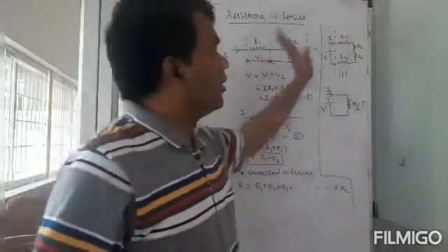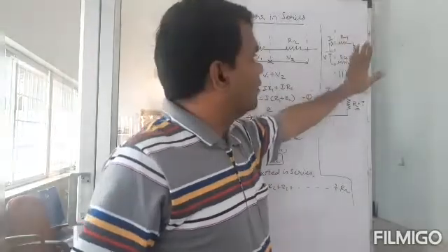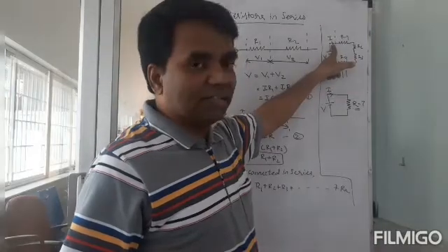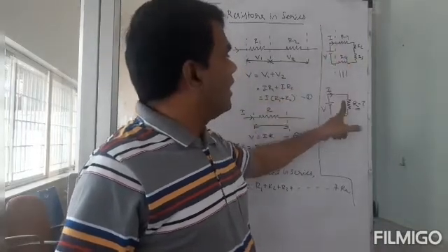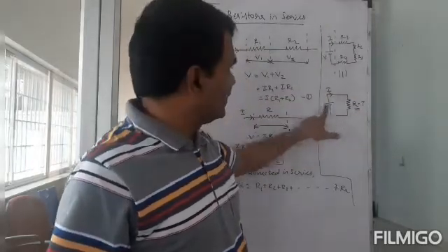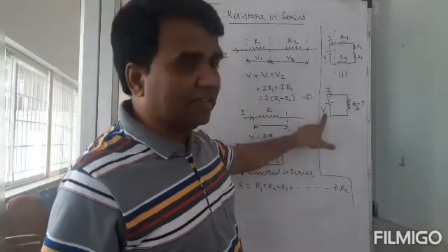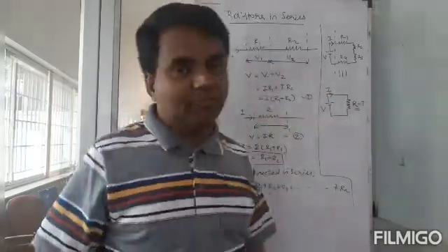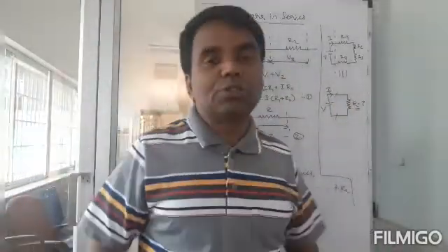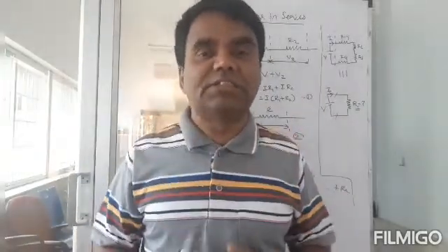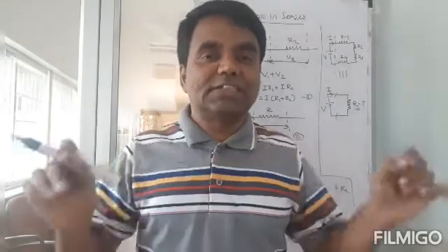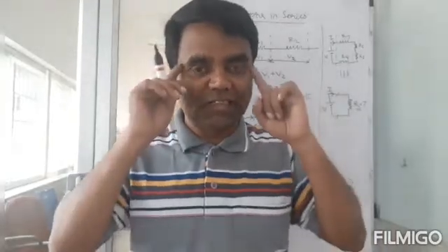So whatever be the complexity of the circuit, whatever be the circuit here, this is going to draw a current I, a certain amount of current, 10 amperes or whatever. My question is, if I replace the entire thing with this one resistance, then the battery I have here, I'm going to have the same battery here. That should supply the same current if I connect it between these two points. So whenever they ask you to find effective resistance, keep this in mind. If you want to figure out whether resistors are connected in series or in parallel, you just have to keep just this thing in mind.